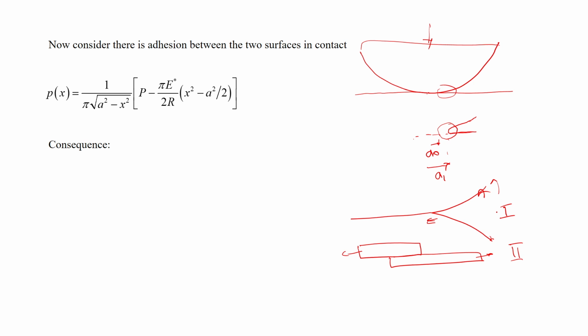In the mode 1 case, there is a pressure applied here. So it is compressive in this zone at the middle and it becomes tensile outside. Close to the crack tip the stresses become tensile, and towards the middle the stress becomes compressive, that is the way it happens.